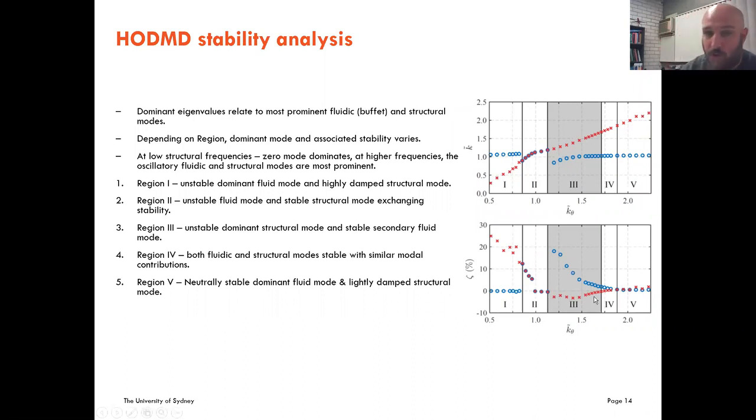But obviously the overall response is stable, so the two must be out of phase from each other to counteract. The wing tries to pitch up, and the shock wave is starting its downward travel, creating a pitch downwards motion to keep a nice, stable oscillation.